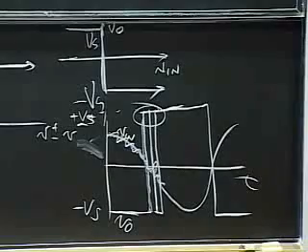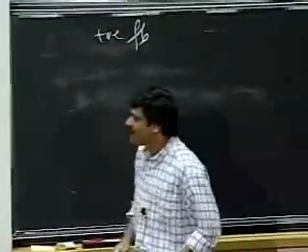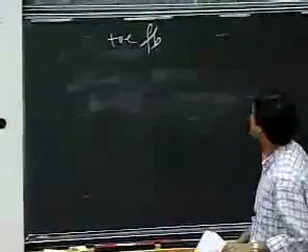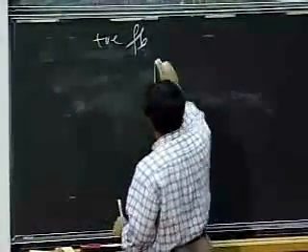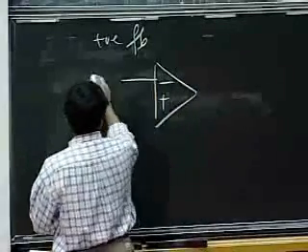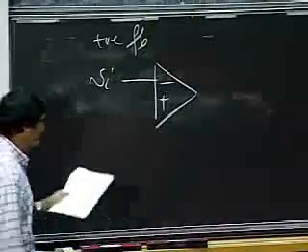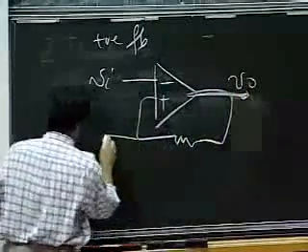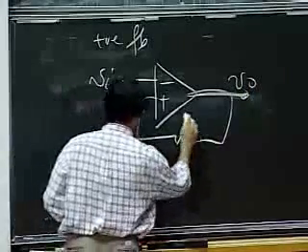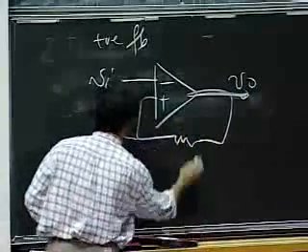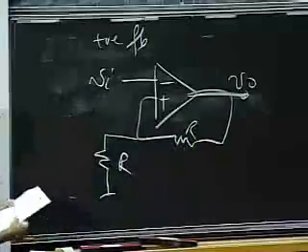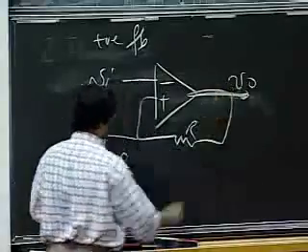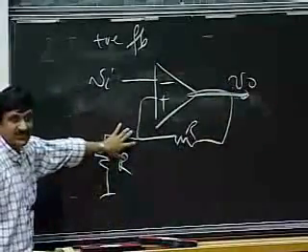So what we're going to do is use positive feedback. I'm going to build you a circuit that shows that we can eliminate this for small noise on the input. So let's build the following circuit. I still feed Vin to the negative input, but this time around, I give it some positive feedback. I feed back a portion of VO to the positive input.